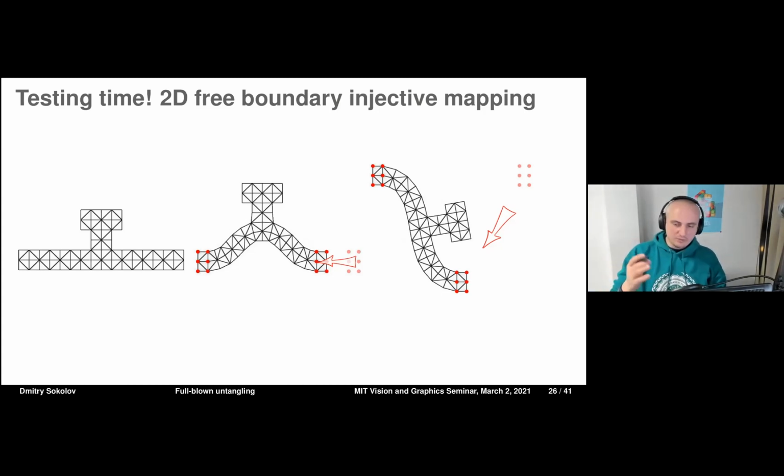All other vertices are free to move. The result is very intuitive for a human. Under compression, the object has chosen one of two possible configurations, towards the top or towards the bottom. And in the bend test, the object behaves exactly as if it was made of some elastic material. But all this is derived from the theory of elasticity. So we rely on works by John Ball. We have a hyperelastic material here. Both our distortion measures are invariant to rotations, so check how the geometric details in the middle of the piece are nicely rotated.